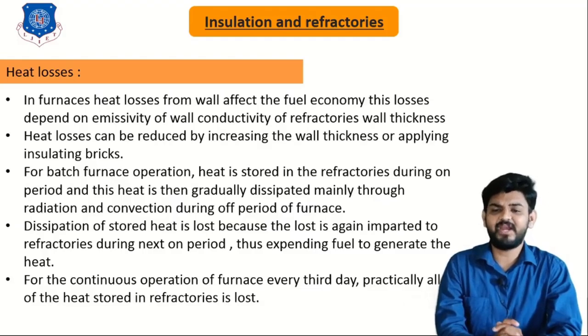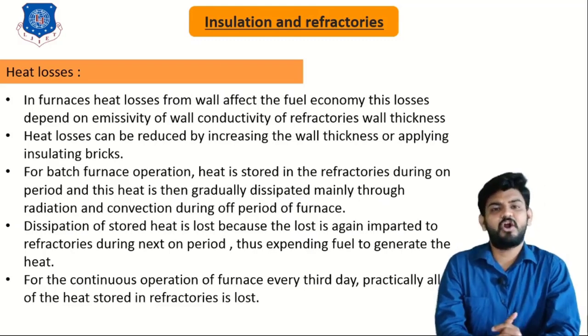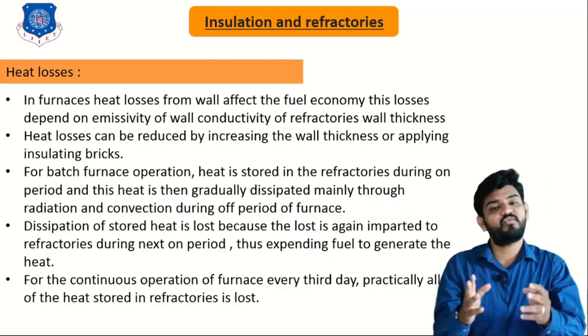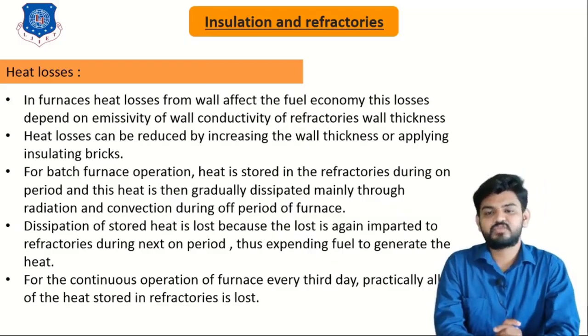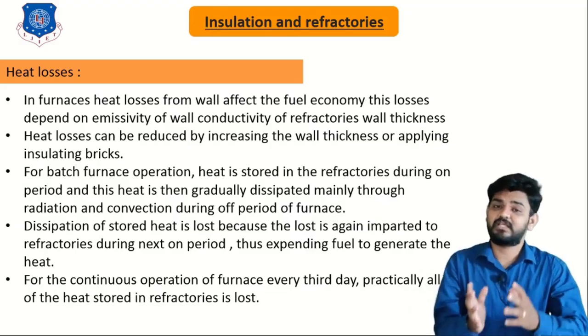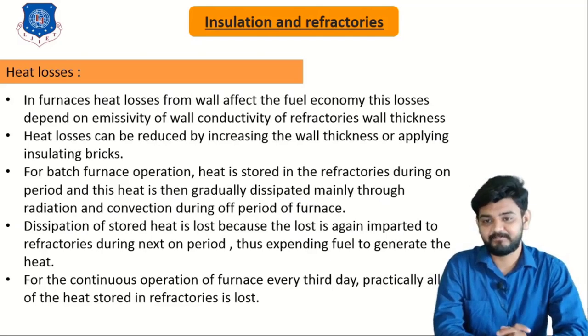These losses depend on the emissivity of the wall, the conductivity of the refractory wall and the thickness. So the loss in heat is going to affect the fuel economy, and these losses basically depend on the emissivity, the thickness of insulation or refractories and the conductivity.